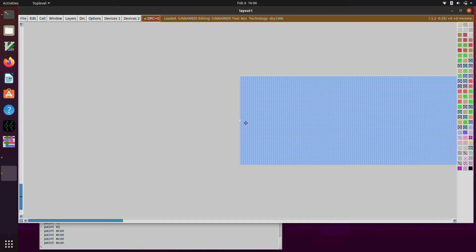And we can make a label by going :label, and then the name of the label. I'm going to call it A, like we did for the schematic symbol. And then the direction we would like the label to appear relative to that little plus sign, which is going to be west. And that should create our label. Now, unfortunately, the font is very, very small by default, and that probably is relative to the very small, very fine grid size.